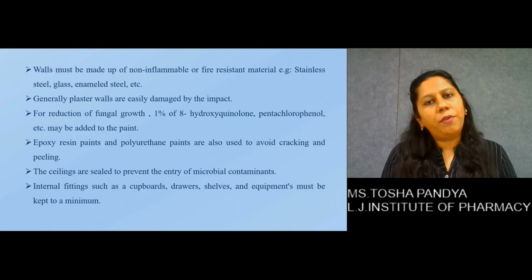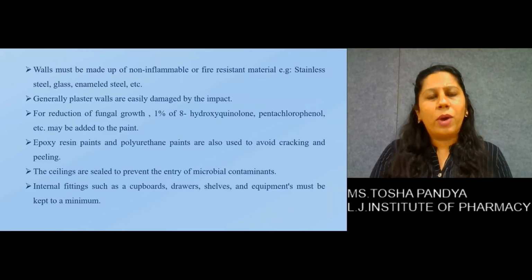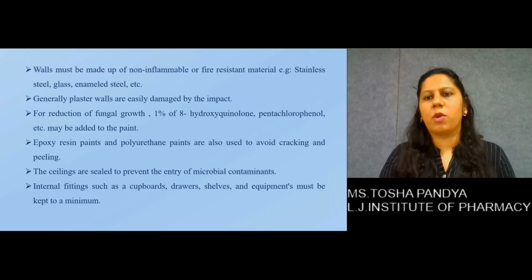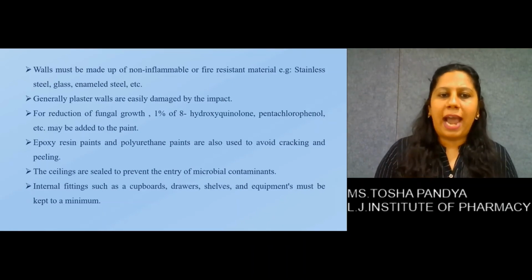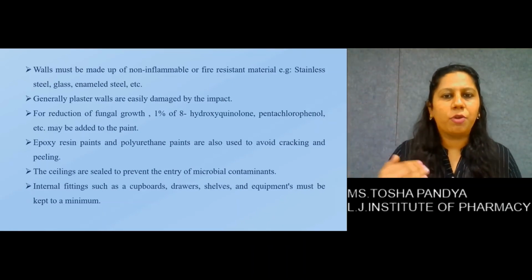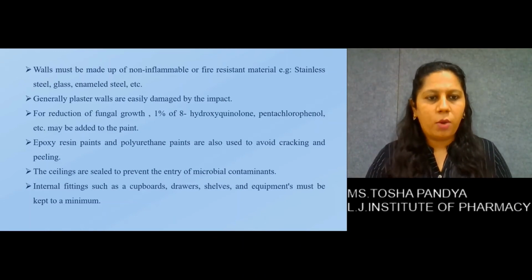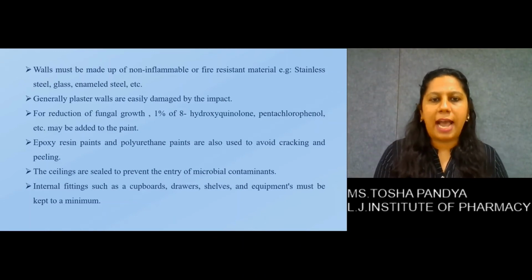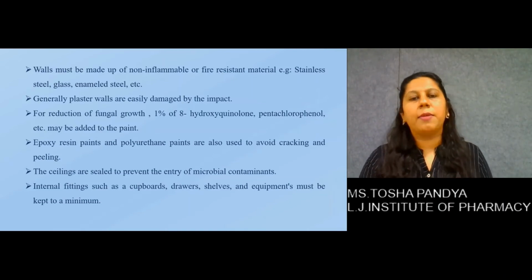Now for the reduction of fungal growth, you can add 1% of 8-hydroxyquinoline, pentachlorophenol, etc. to the paint. The paint should be incorporated with these materials in order to avoid fungal growth. Epoxy resin paints and polyurethane paints are also used to avoid cracking and peeling.